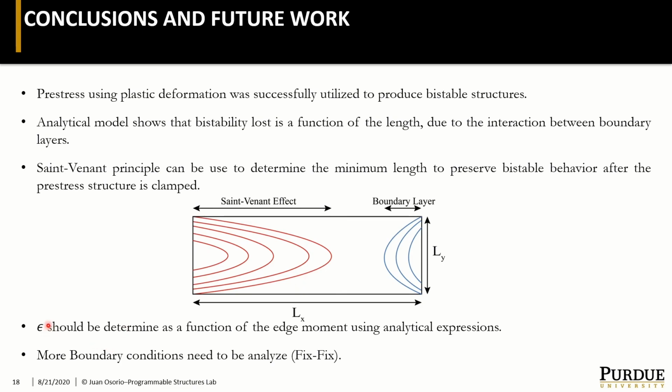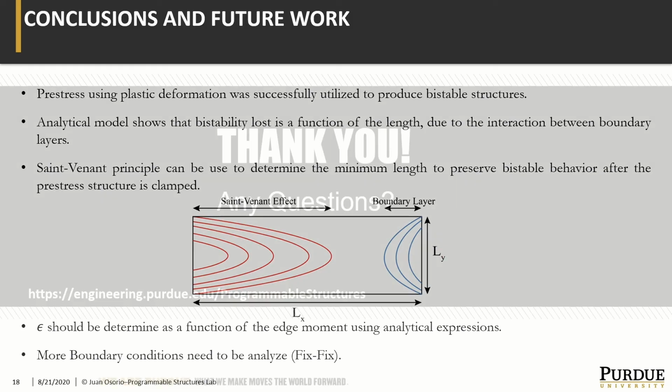For our future work, we'll need to determine the importance of epsilon and the dependence of the prestress and the edge moment required to clamp the structure on this parameter, as we have discovered that it has a huge impact. And also we could test more boundary conditions, for example, one of the most popular ones for this type of element, that is fixed boundary conditions.